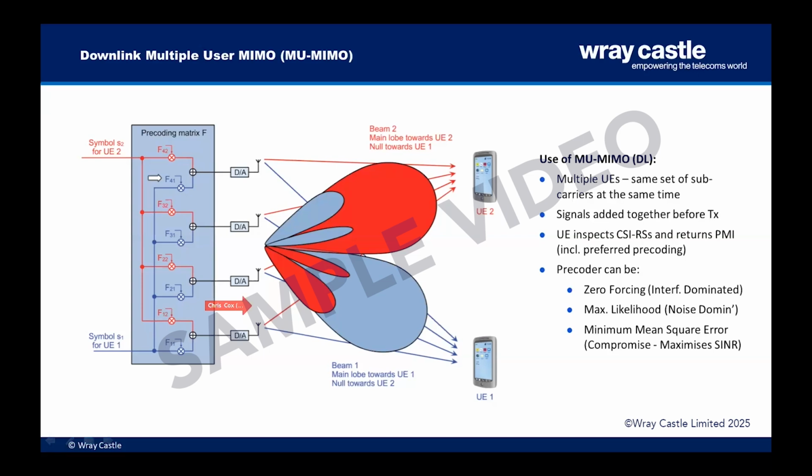We have applied pre-coding weights to the antennas to adjust each of the amplitudes and phases individually. And by doing that, we have got 4 blue rays traveling towards mobile number 1, which will arrive in phase with each other, thereby creating a main beam which points towards mobile number 1.